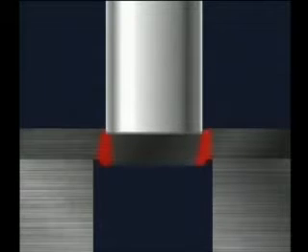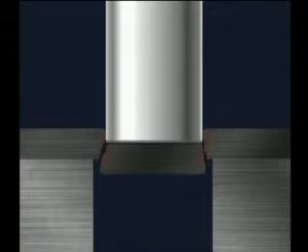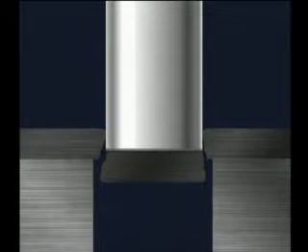During punching, the stock is stressed between the cutting edges of the punch and the die. As the punch penetrates the material, stresses build up until fracture occurs. Close inspection of a die-cut edge of sheet metal stock reveals a burnished edge where the punch penetrated the stock, followed by a rough edge where fracture occurred. Mild steel generally separates when approximately 1/3 of the stock thickness has been penetrated. However, when harder materials are die-cut, penetration by the punch may be less than 1/3 the material thickness, and softer materials may require almost full punch penetration before fracture occurs.